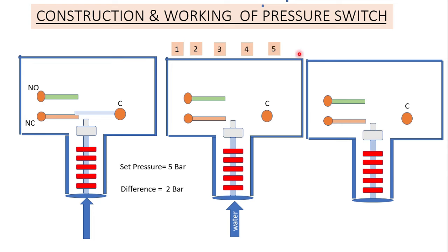When it reaches 5 bar, at that condition the micro switch will get operated by the spring mechanism because of this water pressure. So now its contacts become changed.